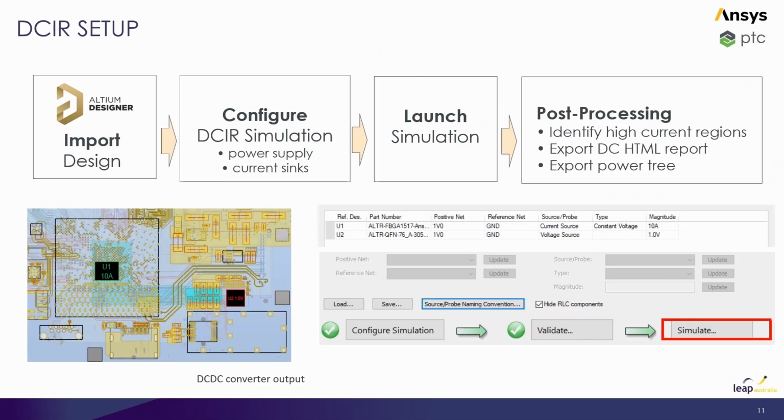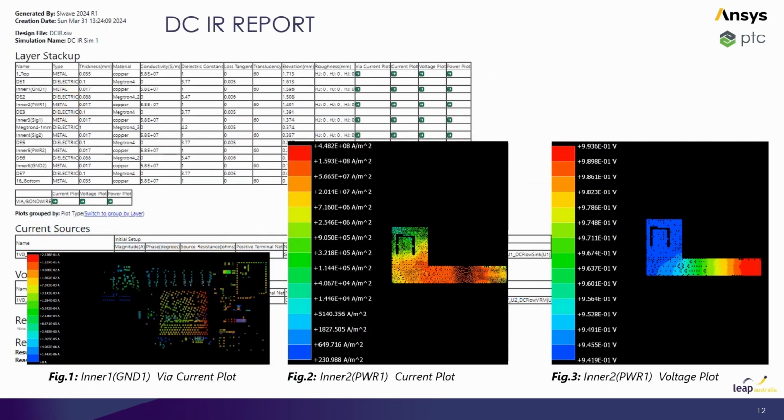That's the DCIR setup. I just quickly go over it. Not just good for delivering clean voltage to your consumers, also good to avoid current crowding and hotspots in the power, so that the thermal design is a little bit better on the PCB.